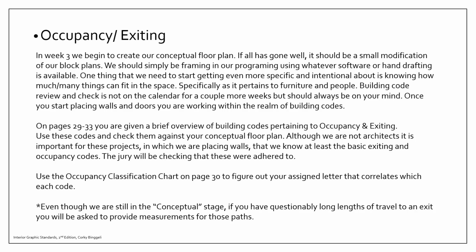So they always give the two within the diagram that's shown below 5.15. There's a without sprinkler and then there's a with sprinkler. So for our project, it's as easy as saying my building is sprinklered, and then in your reflected ceiling plan, you would show your sprinkler heads every, I believe it's 8 to 16 feet, but it depends on the space. So easily you can add footage there if you do have some of those longer lengths.